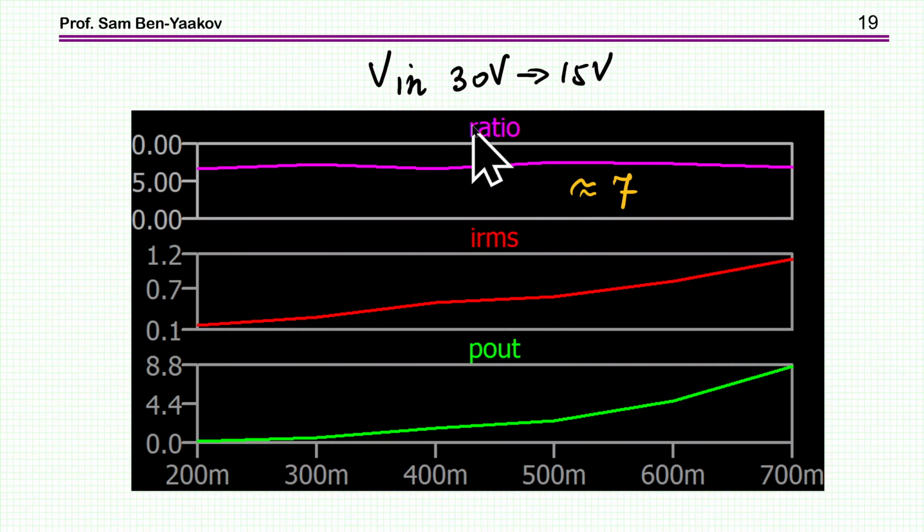I did another run in which I've changed the input from 30 volt to 15 volt. And again, we see the same behavior. And again, since I have not touched the inductor or the frequency, then this ratio should be about the same. And indeed, it is about the same.